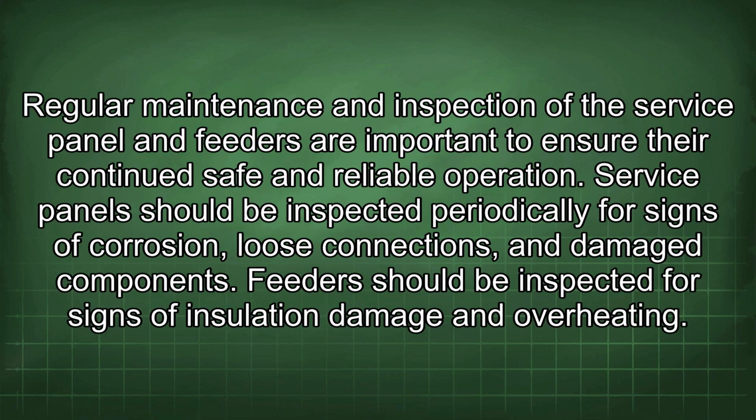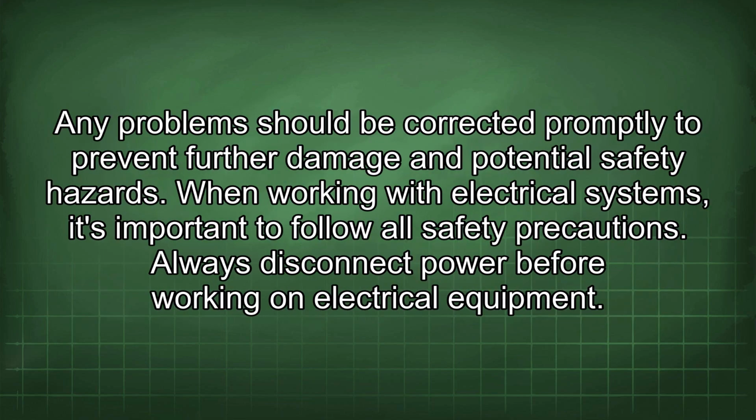Regular maintenance and inspection of the service panel and feeders are important to ensure their continued safe and reliable operation. Service panels should be inspected periodically for signs of corrosion, loose connections, and damaged components. Feeders should be inspected for signs of insulation damage and overheating. Any problems should be corrected promptly to prevent further damage and potential safety hazards.